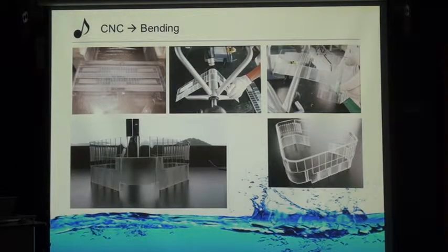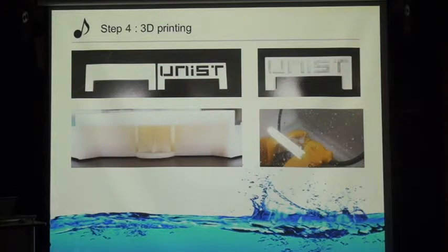And then we used an acrylic plate for the CNC machine, and then used an industrial dryer for bending. This part must be fitted with LED, so the inner part is structured using 3D printing, and the revolving door part is also complex, so we used 3D printing. But as you know, after 3D printing, the processed goods also need finishing. So we used water and NaOH to eliminate the supporter.